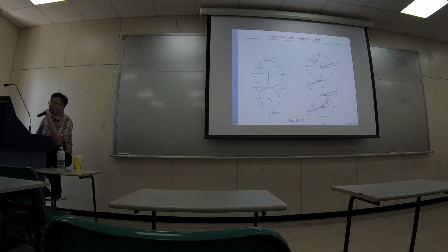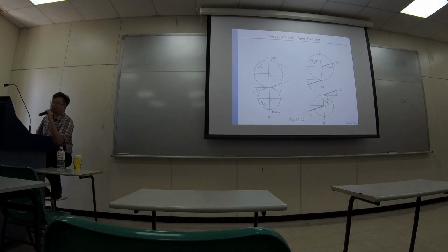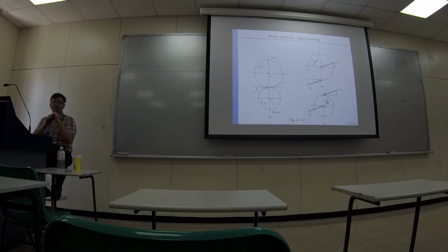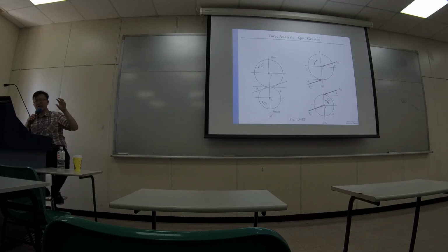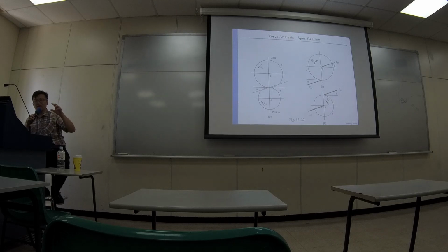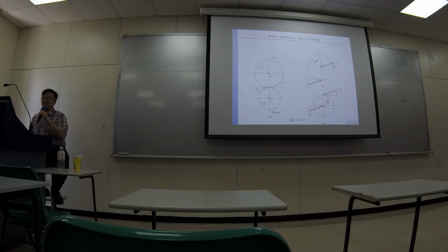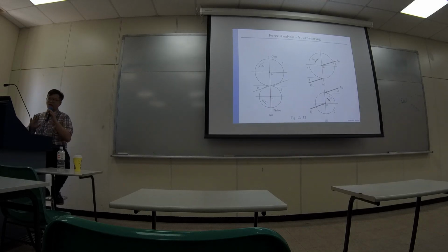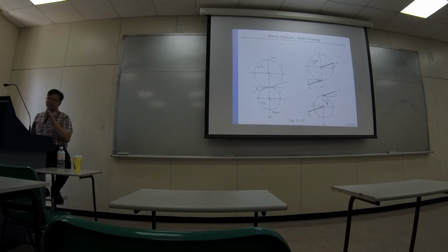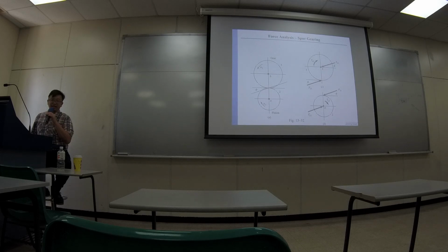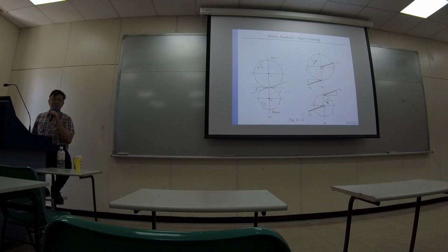So in order to have a balance of force, at the center, that's where your gear is installed on a shaft. There's always a shaft. So there's a reaction force at the center of the shaft. Assuming there's no other forces, then the reaction forces must have the same size, exactly opposite direction. So you have balance of force.